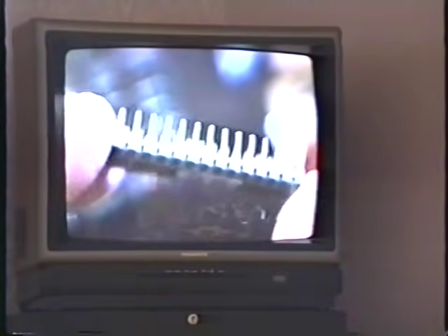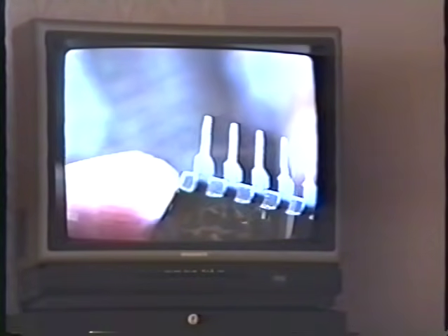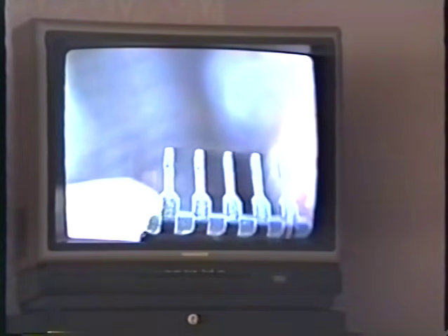The game was still working perfectly, just the images were messed up. When you get the chip out, look at the pins. Are they clean and shiny like these ones? No problem here. But if you see nicotine and dirt and stuff like that on them, like this pin right here on the corner, you can see a little bit of dirt on them. Take a pencil eraser and carefully clean them off.